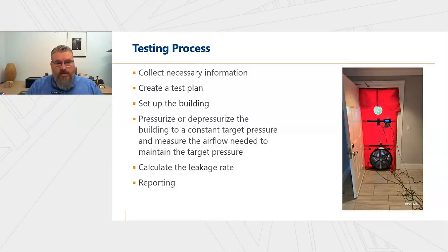And then you get the number that everybody is looking for, and that's that bottom line. What was the leakage rate at 75 pascals? And is it below the maximum allowable? And that's, of course, if you're doing quantitative testing for code compliance or meeting the spec requirement. Otherwise, maybe that's just a number that you record and you're going to compare it after you make repairs to the building, or if you're doing diagnostic testing, you may not really care about the specifics of that number at all. You're just trying to pressurize or depressurize.